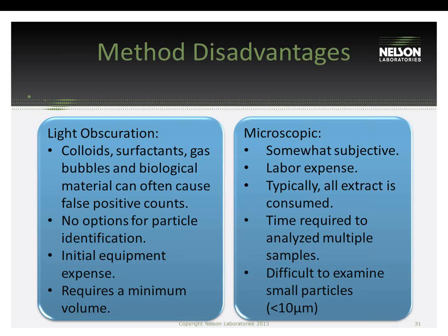The microscopic, however, is somewhat subjective. We currently have 4 analysts here at Nelson Labs who size and count particulates using the microscopic method, and we do experience up to about a 10% difference going from one to another when counting the same sample. While that may be accepted, it's significantly more error than we would experience when using the light obscuration method.